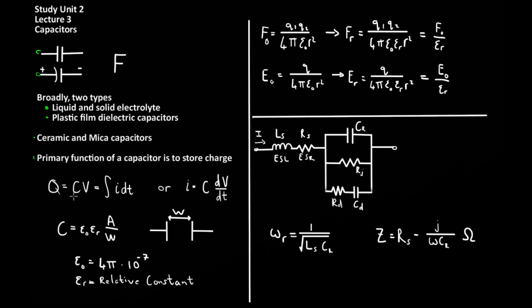It should be seen here that the current can be expressed in terms of the capacitance and the voltage without needing to take the amount of charge stored into account. This can be done by equating these two sides of the equation and solving for the current. Here the current is expressed as the capacitance multiplied by the change in voltage with respect to time across a capacitor. The value of the capacitor is a function of the geometry of the capacitor as well as the electrical properties of the dielectric between the parallel plates or parallel surfaces in the capacitor.